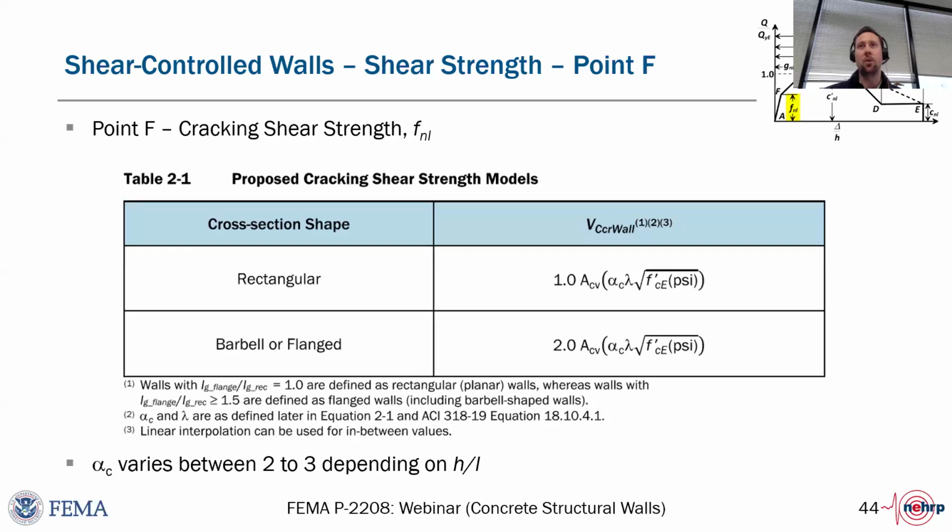Yeah, so generally, the overarching provisions for lap splices, hopefully I'm getting the section number right, I think it's in section 3.5 of ACI 369.1. But in the broader provisions in chapter 3 of ACI 369, it tells you how you need to check adequate or inadequate. You'll find in going through those, there's specific provisions for columns and beams. And then there's a general statement for other members.